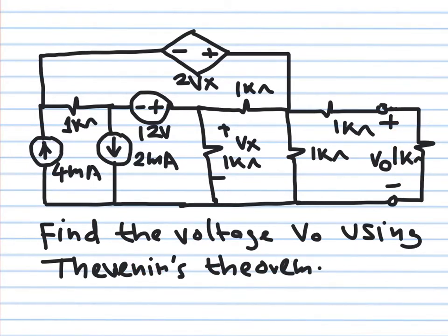Okay, so what's happening here? When this is used, I usually take this as my load and I build a Thevenin equivalent seen from this side. Okay, so I'm not gonna be including this resistance here to this side. So I will find R Thevenin looking from this side here. So I need V Thevenin and I need R Thevenin. So don't make the mistake of including this load resistance in your Thevenin. This one's going to be connected to your load analysis.